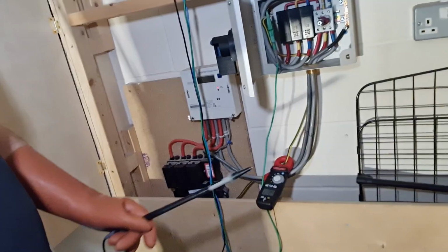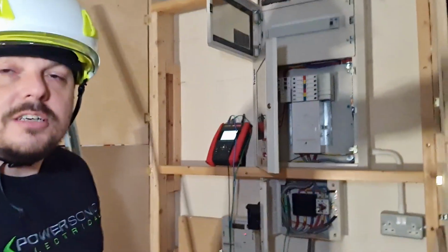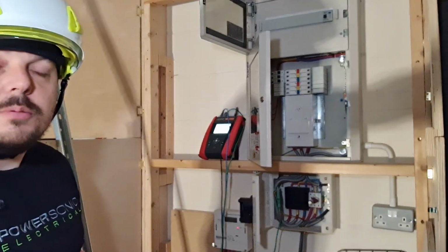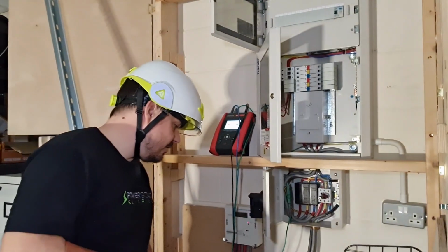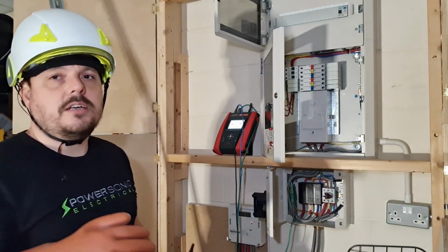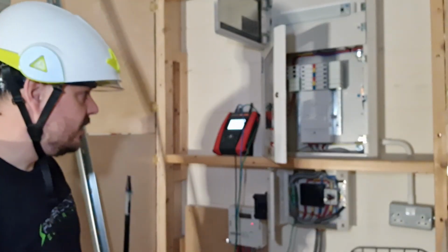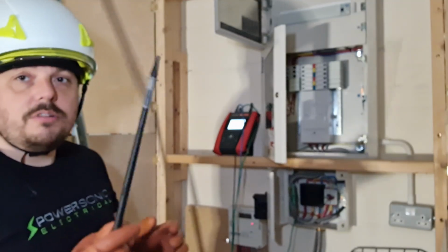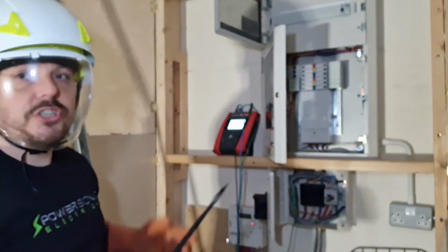so this prevents that. You'll see I've got the clamp meter on there, and I'm just checking that the current flowing in the earthing conductor isn't of concern. So we've got that set up ready and recording, and at the minute it's 0.1 milliamps. So there's next to nothing on there as we would expect, and it was the same on the DC range as well. So now I can get on with doing the test with my extended probe, face shield down, and yeah, let's just run through it.